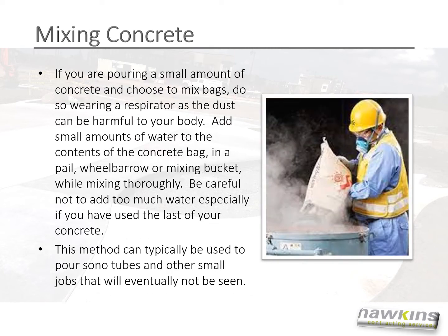Mixing concrete. If you are pouring a small amount of concrete and choose to mix bags, do so wearing a respirator, as the dust can be harmful to your body. Add small amounts of water to the contents of the concrete bag in a pail, wheelbarrow, or mixing bucket while mixing thoroughly. Be careful not to add too much water, especially if you have used the last of your concrete. This method can typically be used to pour sonotubes and other small jobs that will eventually not be seen.